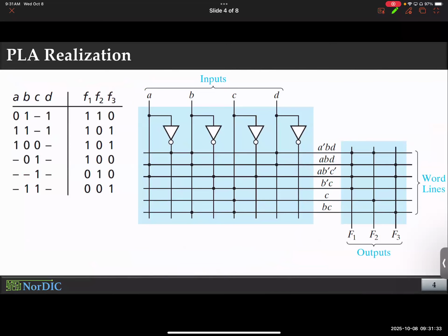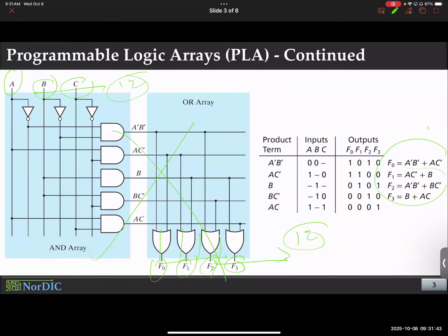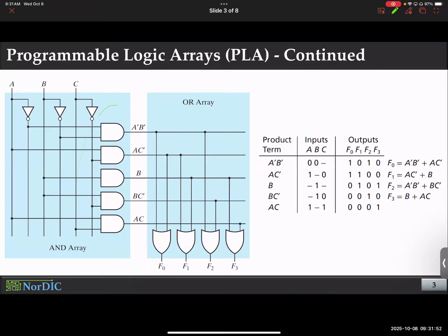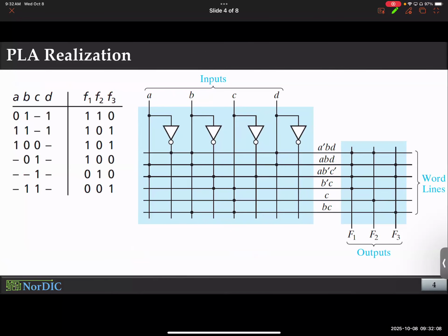One other thing is that this could be an interesting testing ground for your logic systems, but it is not the most efficient, because incorporating logic in this format is not the most area efficient thing to do. It is obviously not the most energy efficient either, because you are distributing it across an array and most of it is unused. This was a classic example: you just had one input that you had to channel, but you are using an AND gate for no reason. That is the signature of most of these general purpose programmable platforms. The programmability and universality come at a cost of not having proper optimization.